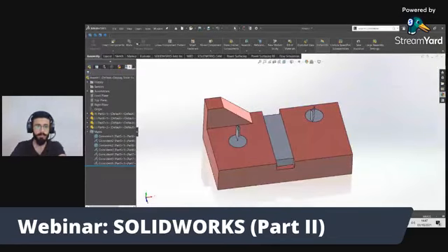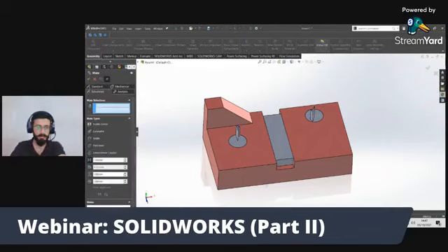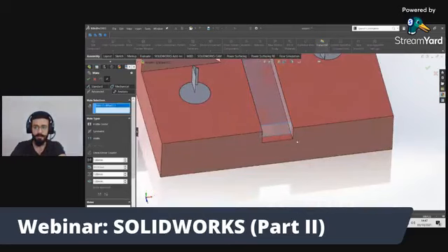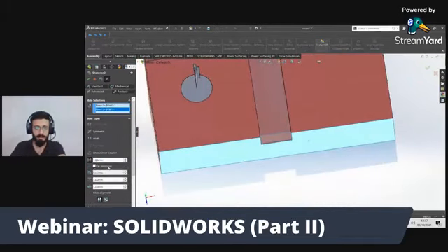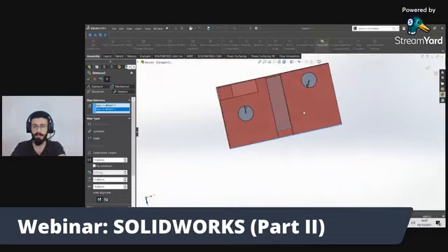Now we will be using the distance mate so you can feel the difference of it. Advance. See this face and this face. There is 1 selected. I will increase it to 11. See, the 11 is selected.